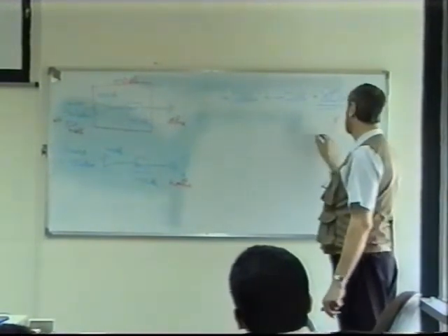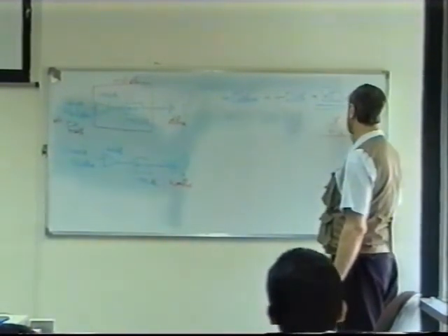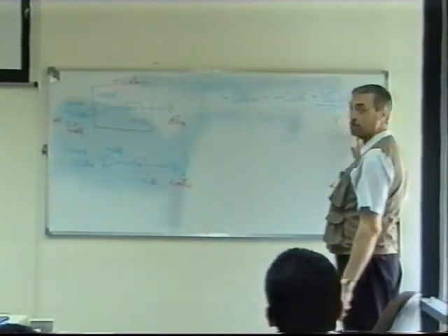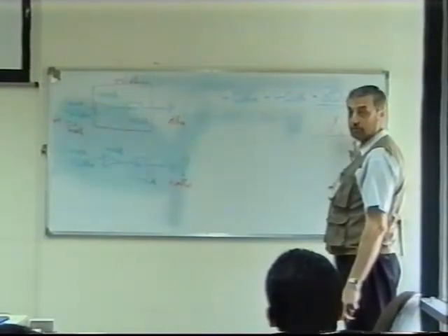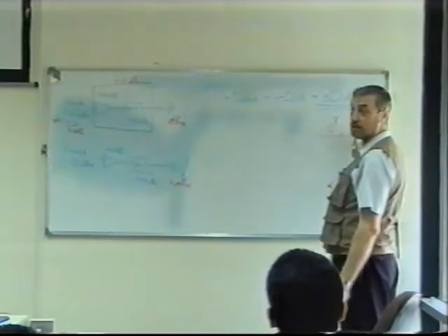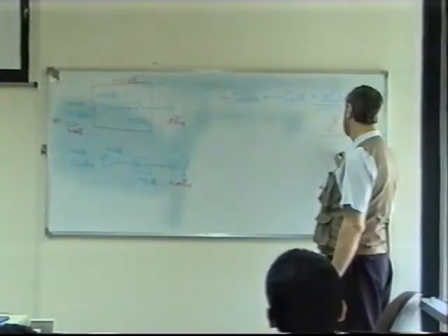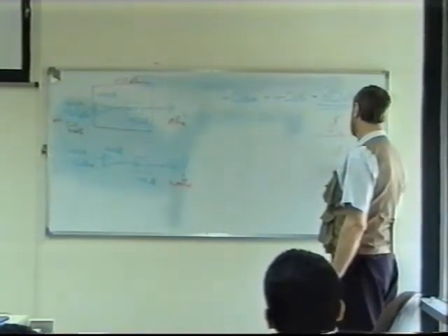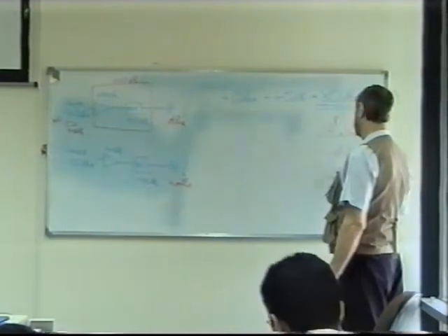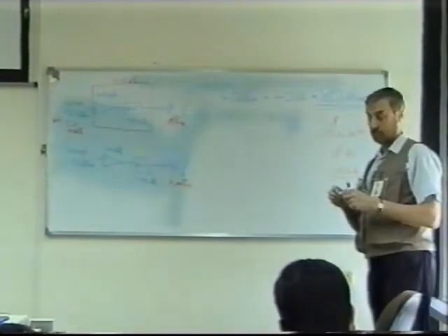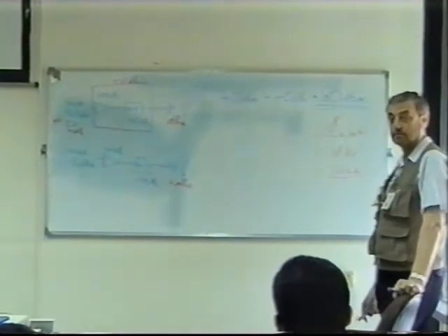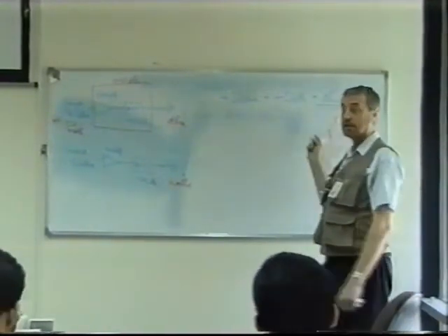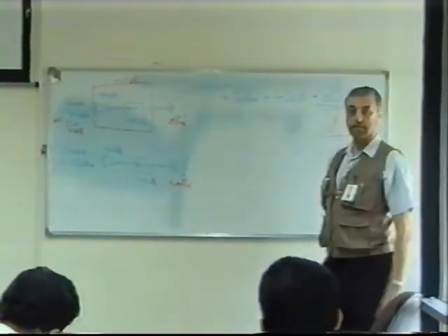Multiplied by 1 milliwatt. We're doing it the other way around. That's 100 million milliwatts. Now, milliwatt, of course, is 10 to the minus 3, isn't it? So this comes to 10 to the power 5 watts, which is 100 kilowatts. If that's what you wanted to do. That's if you wanted watts, yes. But I didn't ask that question. You don't have to do this. That's the answer, 80 dBm.